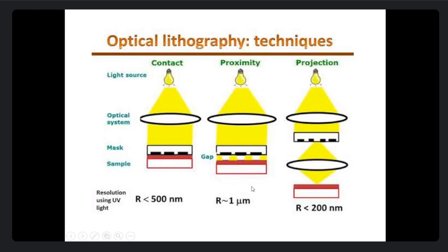regions side by side. Regions means, in case of a chip, the components. So two components very close side by side, because the image spreads, obviously its neighboring image will also spread. So there will be some kind of overlapping or superposition, which you do not want. That means you have to keep sufficient separation between two images.